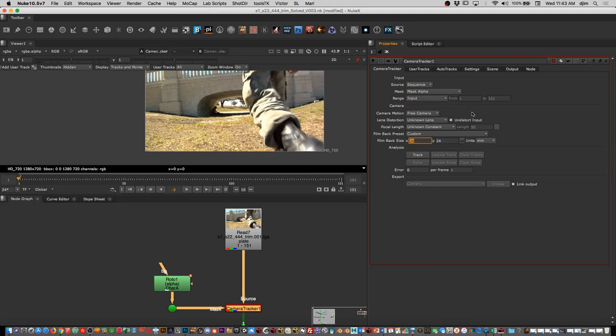The other thing that you could have is in the presets, if you could find the preset here of this specific camera, then you could use that. Now, here there's no preset for Panasonic, so we don't have a preset for that camera. Last but not least, we're done with the data. So what do we do next? We track. All the steps that you need to do, like in SynthEyes, they're in a tab system, 1, 2, 3, 4, whatever. In here, they're top to bottom. You first analyze, so you track it, then you solve it, then you fix the error, and you're done.